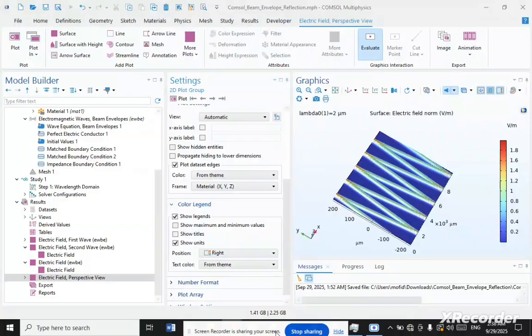And how it works. The first one is field decomposition. The physics interface assumes the electric field can be expressed as a product of a slowly varying envelope function and a rapidly varying phase function, where k is the wave vector. The second one is simplified simulation. By prescribing the rapidly varying phase function, the interface solves the wave equation only for the slowly varying envelope function, significantly reducing the computational resources needed.